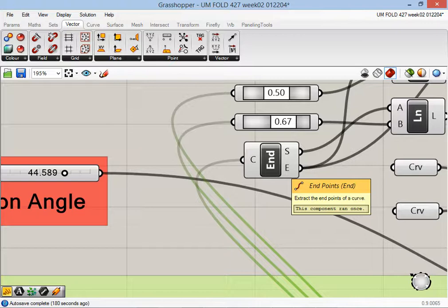No. Well, in Rhino it's orient. So we can reorient the geometry to another position. Now this is going to be a simple orienting of Z0, Z30. Right? Can we do a move tool in Grasshopper? Sure. I'm going to show you orient because that's going to be critical in how we start putting more complex geometry to other positions. Okay? So we're going to use an orient.